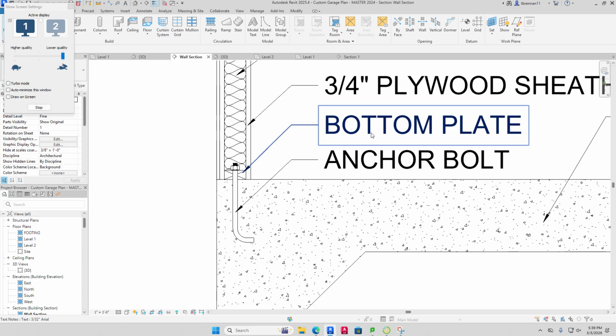And that stud sitting on the floor. You probably know what I'm talking about right now. But the same is true of any wall. Any wall that's in a wood framed house, right here, you've got a stud down on the bottom. Does that make sense? Right? And then to hold it all together, you have an anchor bolt. The anchor bolt goes through here, gets bolted down, and actually turns into here to actually anchor it into the foundation. That's how this works. So all this mechanically works like this.